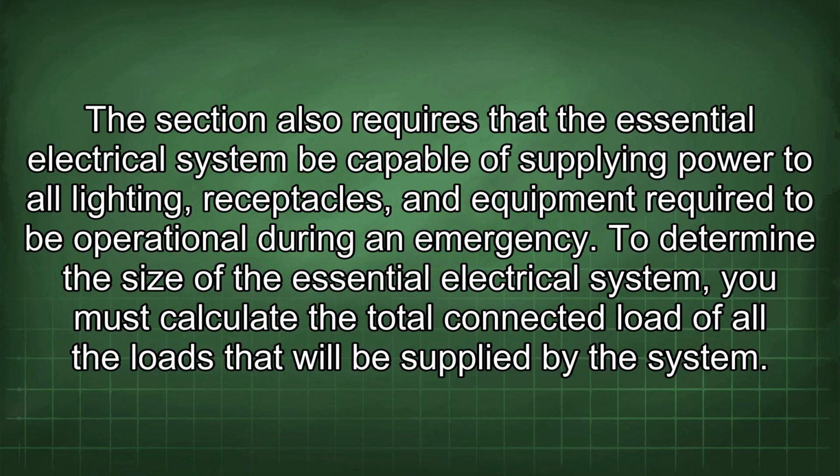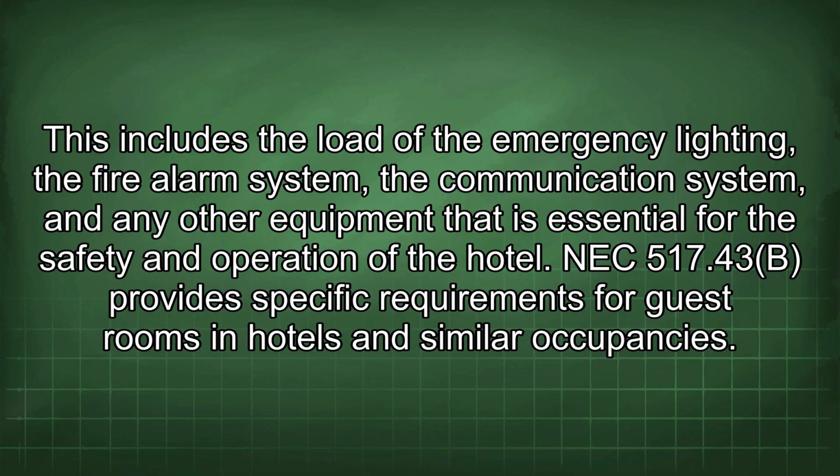To determine the size of the essential electrical system, you must calculate the total connected load of all the loads that will be supplied by the system. This includes the load of the emergency lighting, the fire alarm system, the communication system, and any other equipment that is essential for the safety and operation of the hotel.